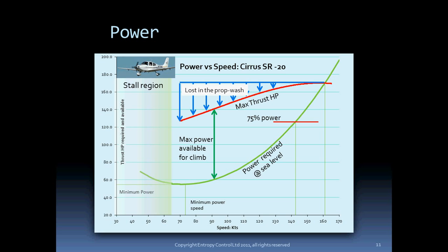But for this aeroplane, let's say we're at 600 foot on takeoff and the engine quits, too low for CAPS deployment. Can we make the impossible turn and land on the airfield? If we fly at 73 knots, as I said, we have about 1 minute to touchdown. A rate 1 turn will get us through 180 degrees in 1 minute, but a rate 1 turn at 73 knots is a very flat turn indeed.